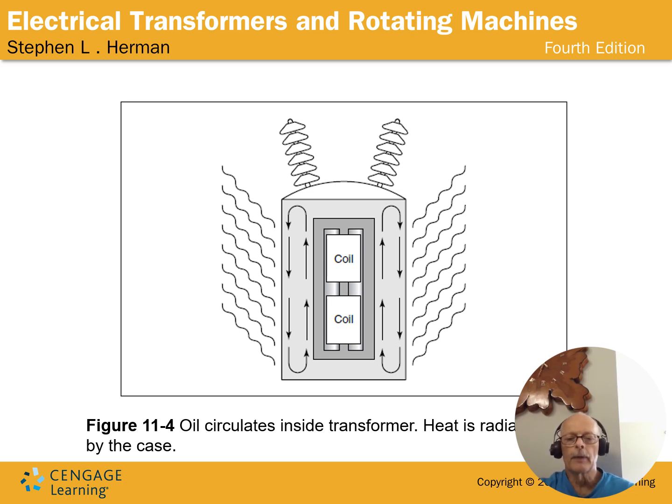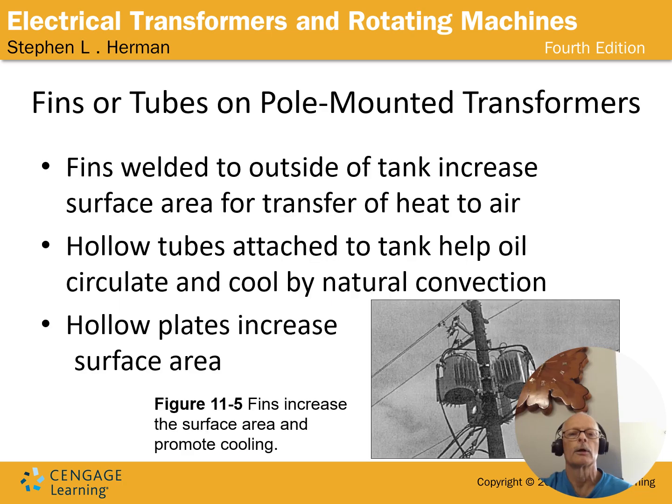But that's because the oil in the housing of that thing was doing a good job of carrying the heat off the core and protecting the metal components, protecting the varnish that's on the wires in the transformer. It's another thing: if the varnish gets too hot, it'll start to delaminate. And when it does, you'll have shorts and arcs, and it'll burn up that transformer shortly.